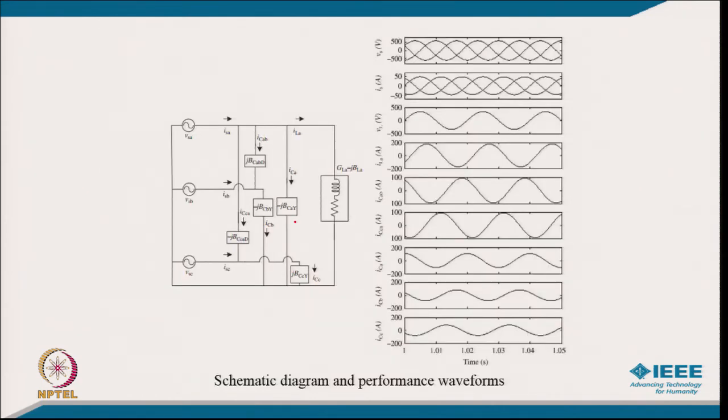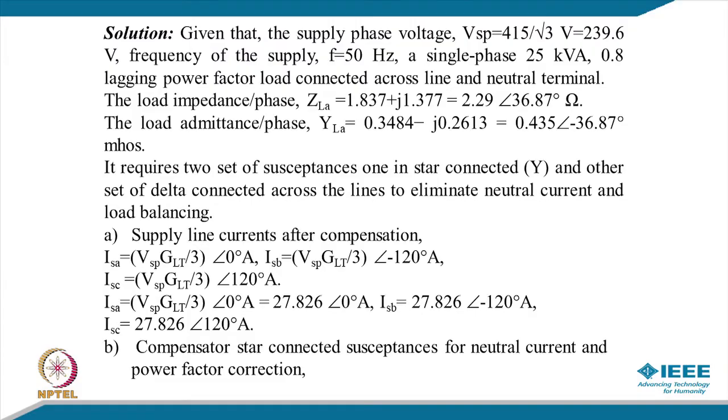And this is the circuit configuration that we have here, realized with 5 elements, otherwise the solution will not be unique. We already discussed this earlier when we were discussing the condition. So, we take 5 elements: virtually 3 in delta and only 2 elements in star connection. So, it becomes a unique solution because there are 5 elements and 5 equations.